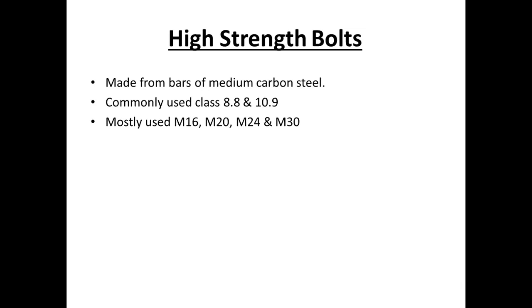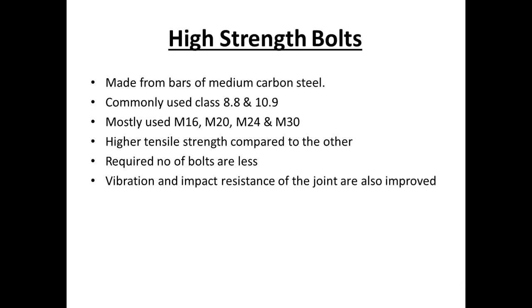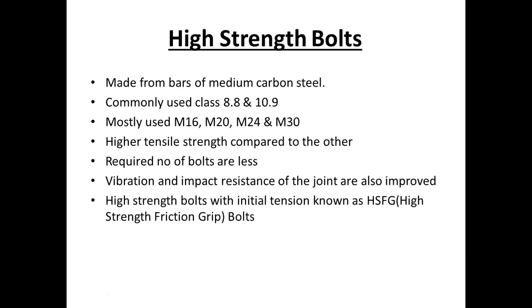Since these bolts have tensile strength much higher than ordinary black bolts, the required number of bolts at a joint is less, right? Next, about vibration and impact: the vibration and impact resistance of the joint is also improved because of these high strength bolts, right?